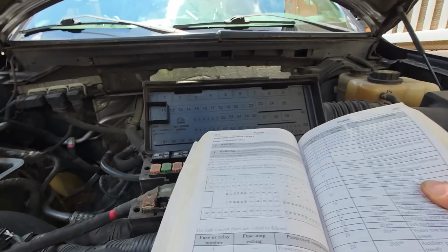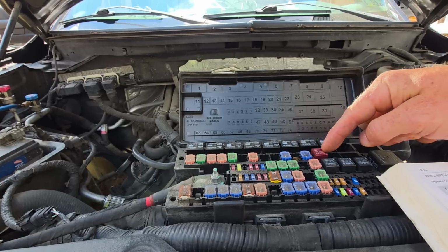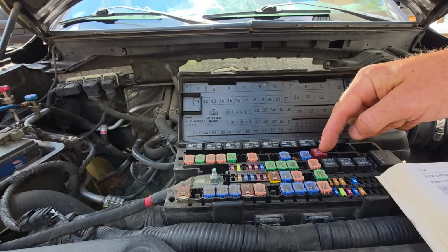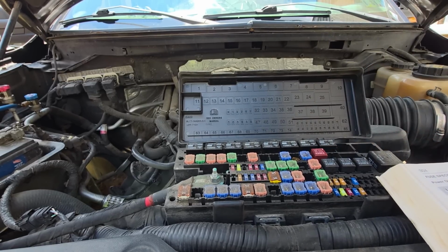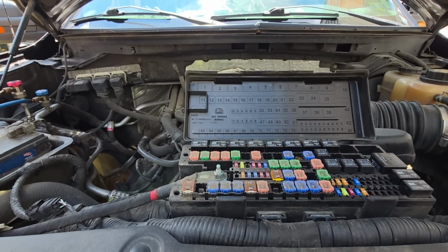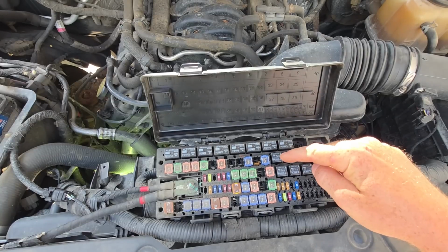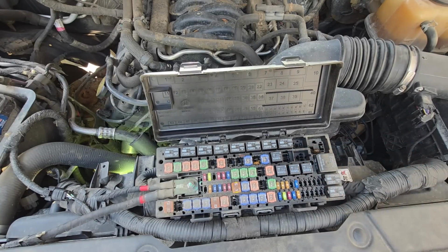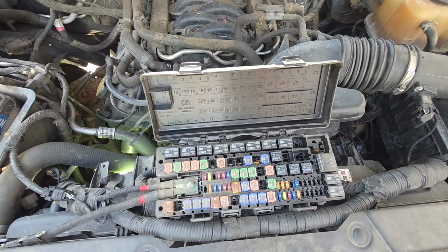Okay, 23, let's see. It's this guy, should be this guy right here. If 23 is the AC clutch relay, yeah, it should be this one. Should be. I hate to touch it with the engine off. So before I touch that relay at all, I'm gonna start it. Because if I touch it and then it starts working, then I know we could have a relay or contact issue that I might mask if I touch it now.